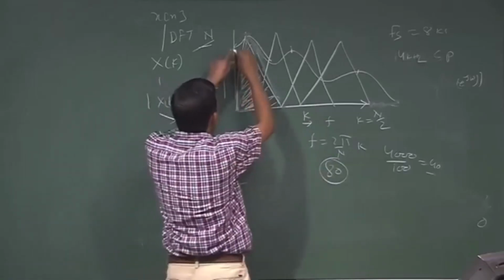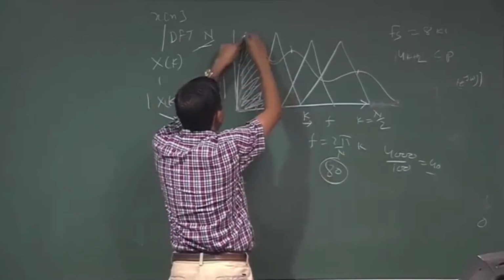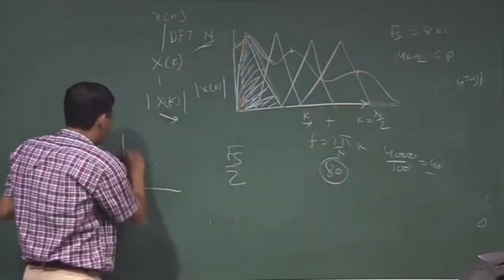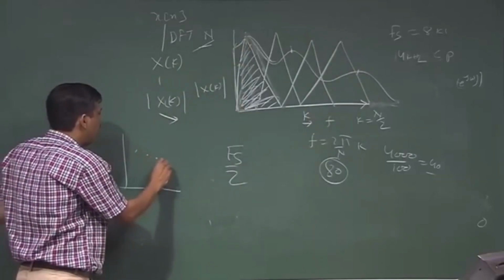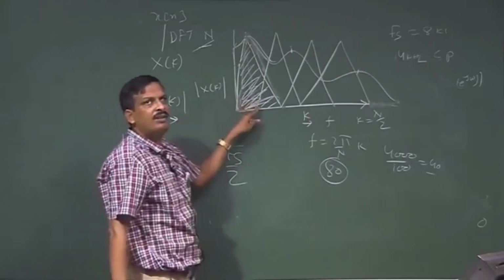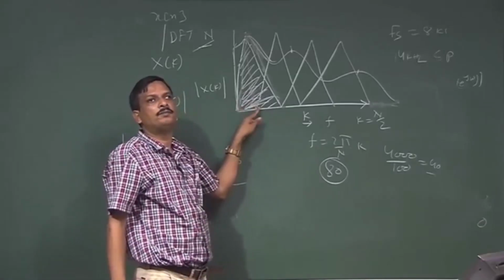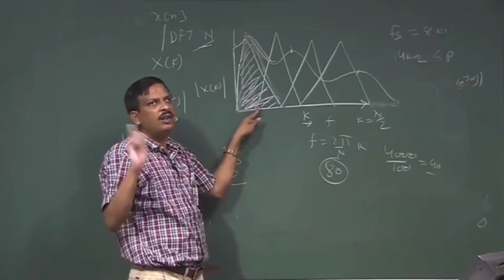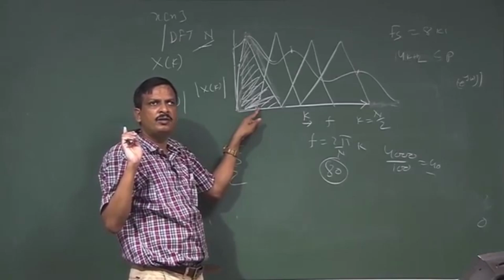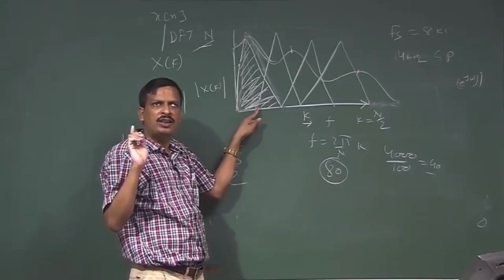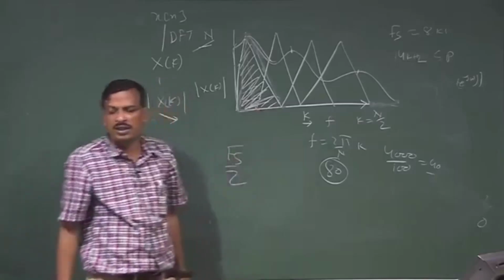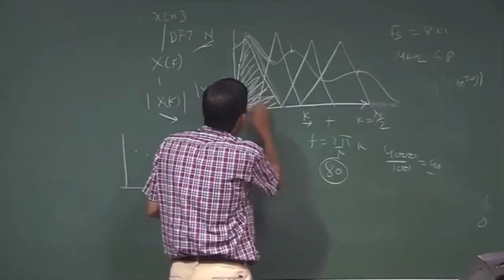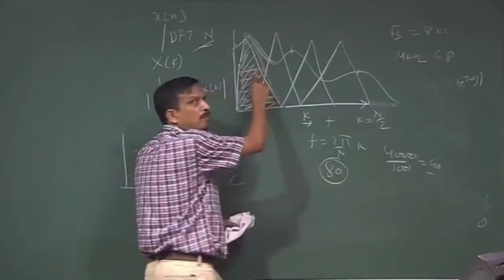So, instead of taking the whole spectrum, I am taking 80 points of the spectrum and finding out the Cepstral coefficients. I can treat that as a signal, pass it through the inverse DFT, and Cepstral coefficients will be generated. Okay. So, information is reduced.